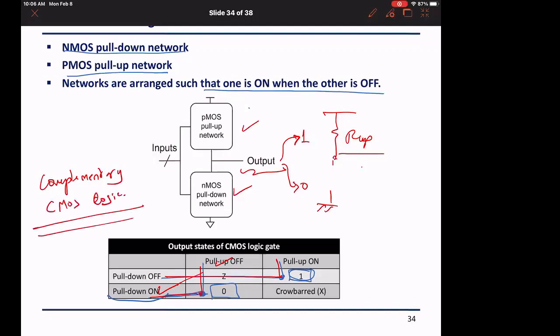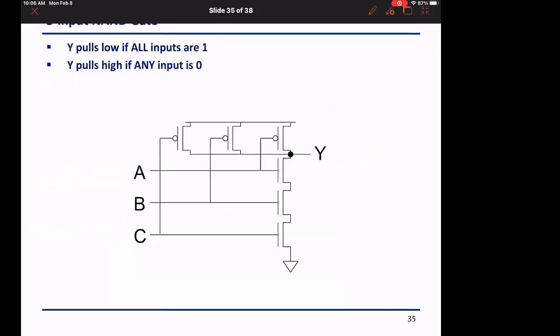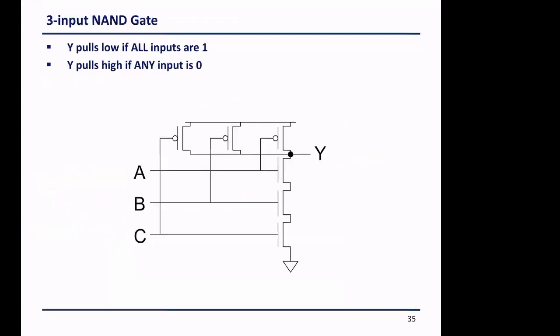Okay, great. Now, if we want to generalize the types of gates that we have studied, we will see that we also have a 3-input NAND, and in this case y is equal to (A and B and C) bar. The way to draw the circuit is as we learned in 3.11. We will start with the function y bar.